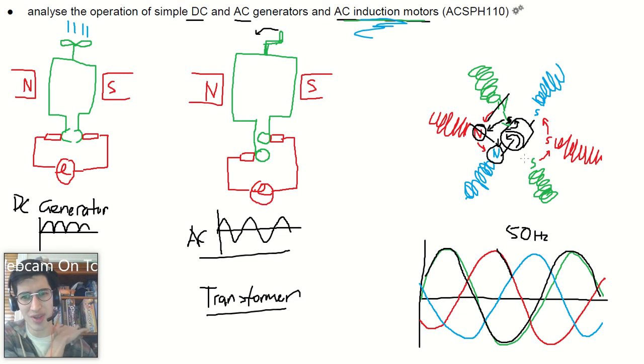Now, this is a complicated setup. You need 3 different sources of electricity to create this motor. Why do we do it? For a start, there's no brushes, no commutator. These contact points here, if we're pretending that this was a motor, because as I said before, it's about the same design. These contact points here, they rub against each other constantly. They wear out. It's a source of sparking. It creates ozone, that kind of thing. Wearing out over time is no good. Over here,